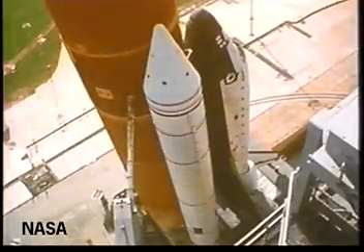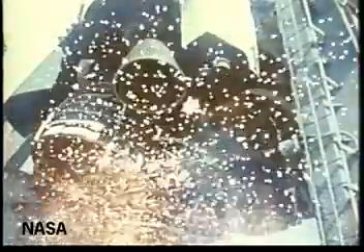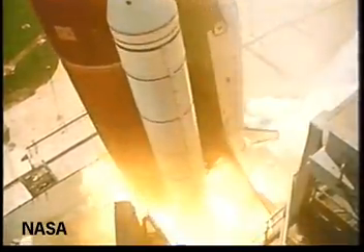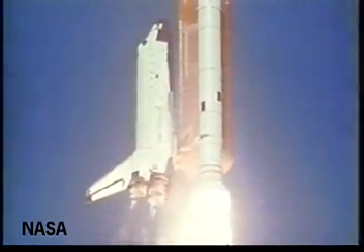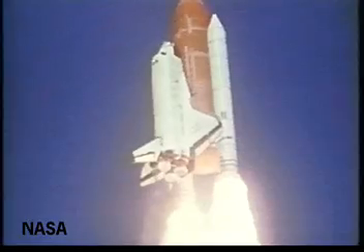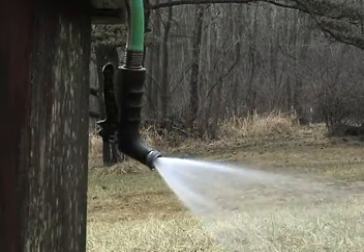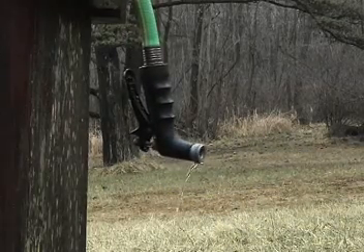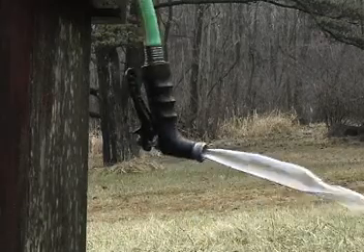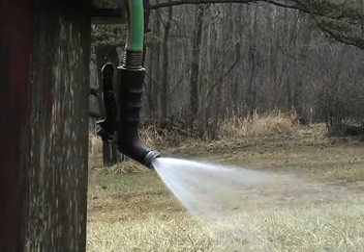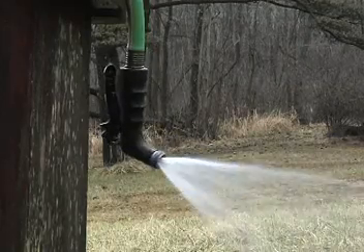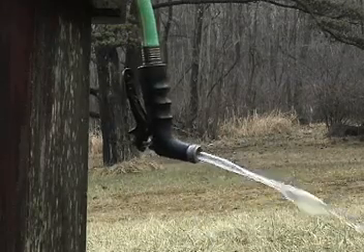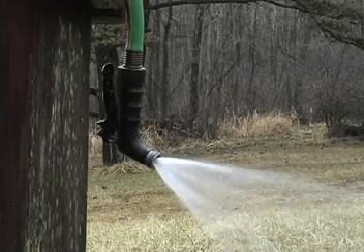In another example, the rocket engines of the space shuttle generate enormous thrust, based on Newton's second law, by accelerating fluid particles to high speeds in the direction opposite the shuttle's motion. When water flows through the spray nozzle suspended at the end of a garden hose, it imparts momentum to the outside wall of the nozzle and generates thrust when the water exits rapidly. The combined effects force the nozzle backward until there is enough strain in the hose material to cause an equal resisting force. When we stop the water flow, these forces relax and the nozzle returns to its original position.